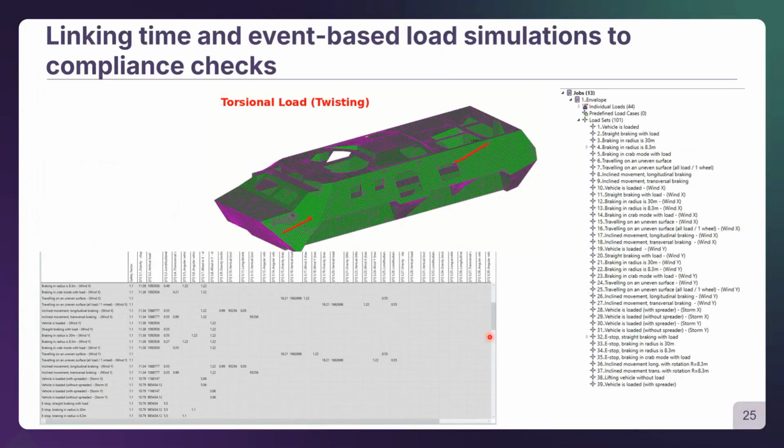You can combine as many scenarios as you like into one SDC project, create load sets, and apply different safety factors. So as you can see here, you can create the matrix with different safety factors, which will result in different load combinations. And as I said, if we speak about ANSYS again, changing these safety factors or creating new load combinations does not require you to recalculate your ANSYS model. So that's something which decreases the calculation time significantly.